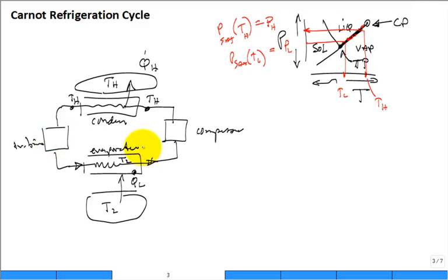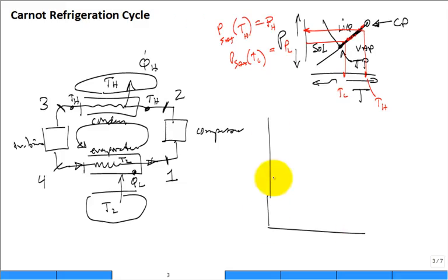Which way does the fluid flow? In that direction. Why do we draw it like that? Because it's going to be lining up with the states on a TS diagram. We typically start the numbering at 1, but there's nothing special about where you start. To be consistent with the textbook, 1 is what comes out of the evaporator and goes into the compressor, then it's followed by state 2, then state 3, then state 4. So everything's going to be tucked underneath, on a temperature-entropy diagram,